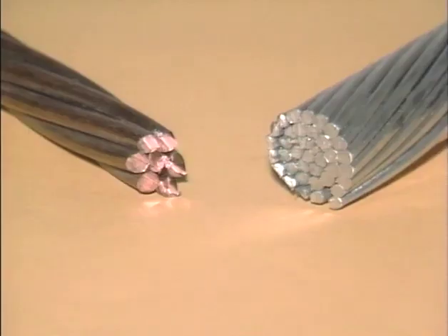But as I pointed out earlier, resistance is determined by the material the conductor is made of and the size of the conductor as well as its length. So let's look at conductor materials and then conductor sizes and see how they influence conductor resistance. Depending on the material used in the construction of a transmission line, its conductivity varies. Now, conductivity is the ease with which a substance allows current to flow. The greater the conductivity of a material, the less its resistance to current flow.